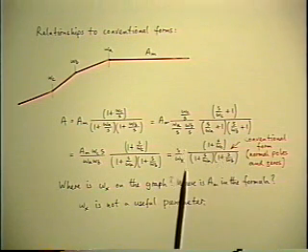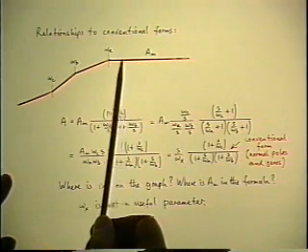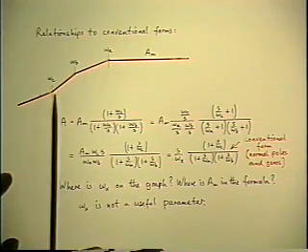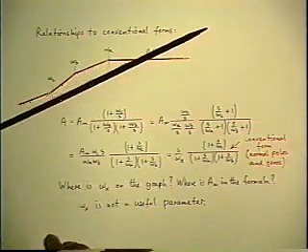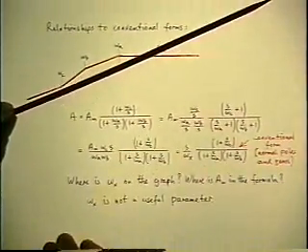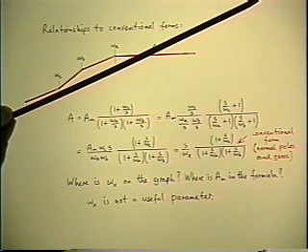So S over omega x must be the zero frequency asymptote. So what that would mean on the picture is you'd let S be so low that it would be even lower than the omega C, and all that's left is this asymptote. Not very straight on the TV, is it? Not on this one, anyway. S over omega x must be what I've identified. So now where is omega x?